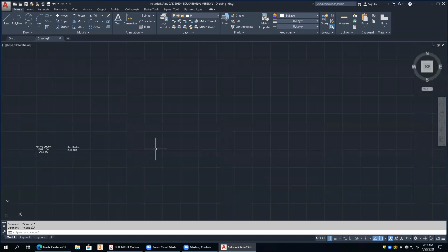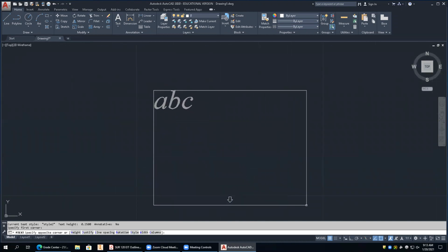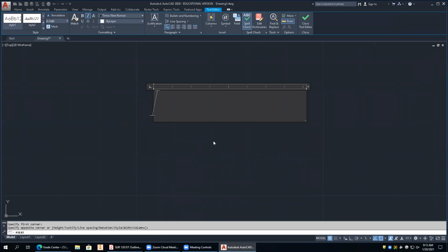M-text is going to work basically in a space. You can think of it like a document. So when we go to M-text, this gives this symbol right here. I usually just pick a point and pick another point to open up a window. Okay. Now you're in what's called the M-text editor. Notice this right now, your ribbon has changed totally. This is called a context-sensitive editing tab. And so while you're working within it, this tab will be in effect. And when you're done with it, you just close it.